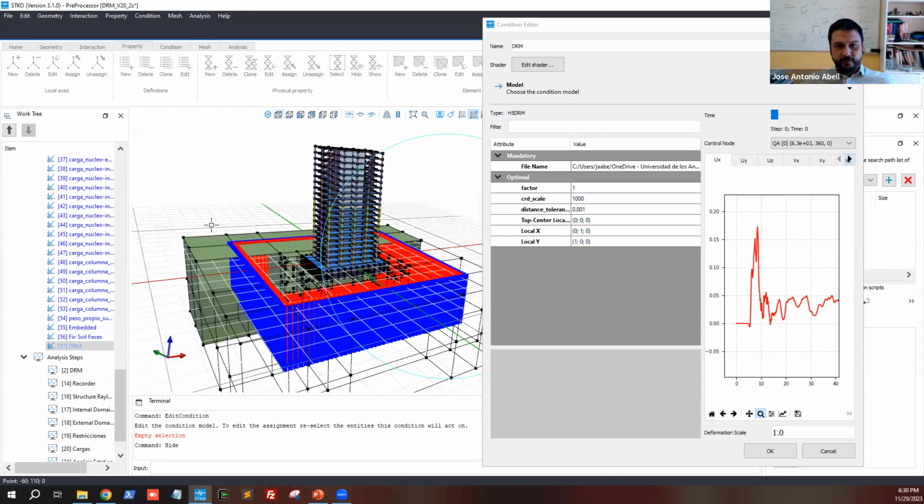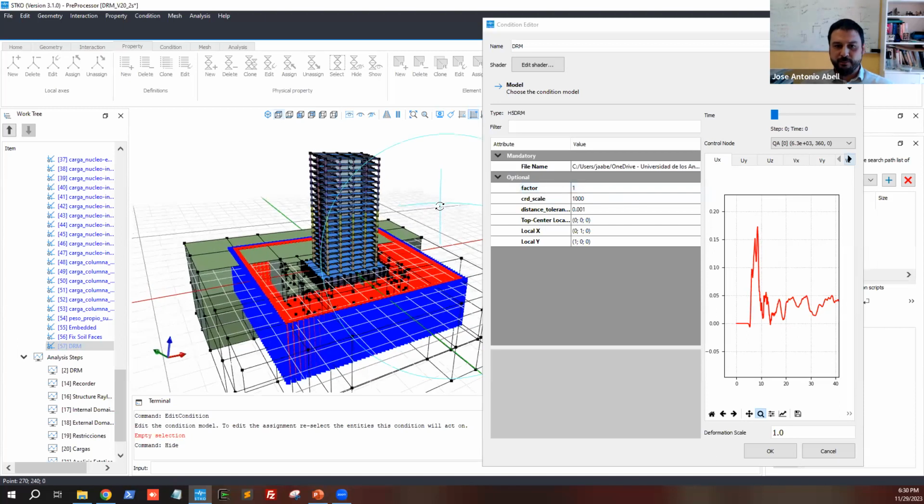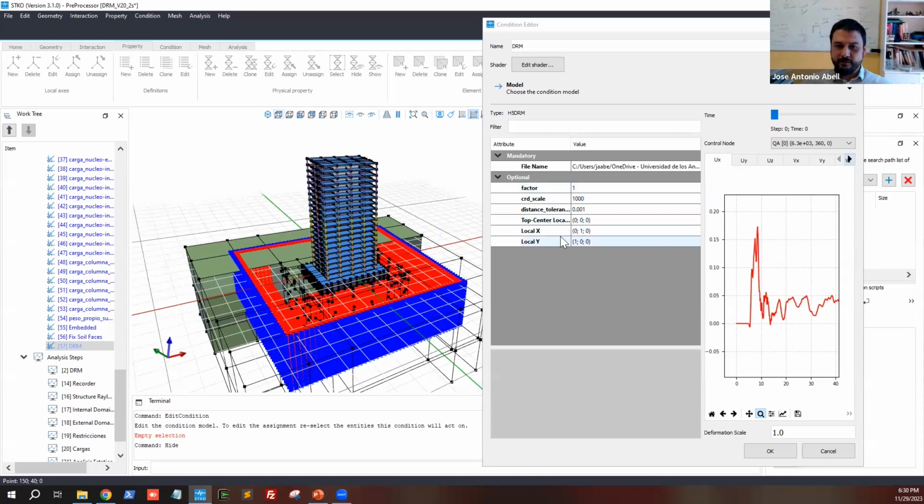And so this little plugin that I have over here helps you place the DRM box wherever you want in the domain, which is crucial if you're sharing data sets. They're not all going to match. So you need some control over what happens with the DRM motion. This plugin reflects, and I'm going to show you the OpenSees command for the DRM after this, the same options. It also gives you the possibility to see what the target motions look like. These are displacement responses at the center of the DRM domain. That's useful to know at a glance that you're using the right data set.